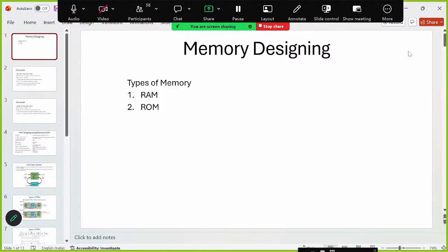And as I told you earlier when we started the synchronous designing topic, in synchronous design, a flip-flop or a latch is called the one-bit storage device. Okay. Following that, when several flip-flops are joined together, they become a register. And when these registers are stacked one upon each other in a specific pattern, this stacking is sometimes referred to as registers or register array.